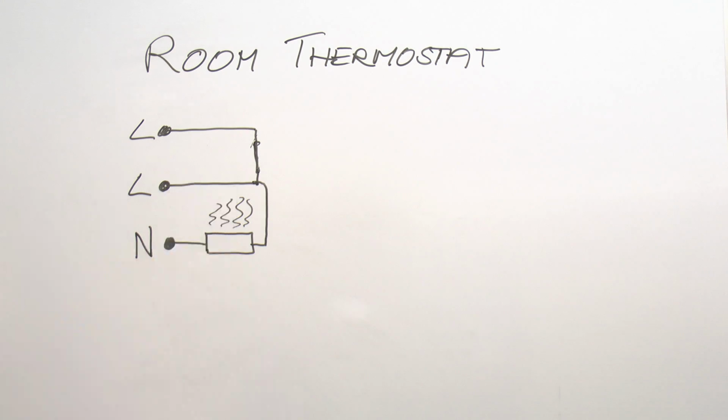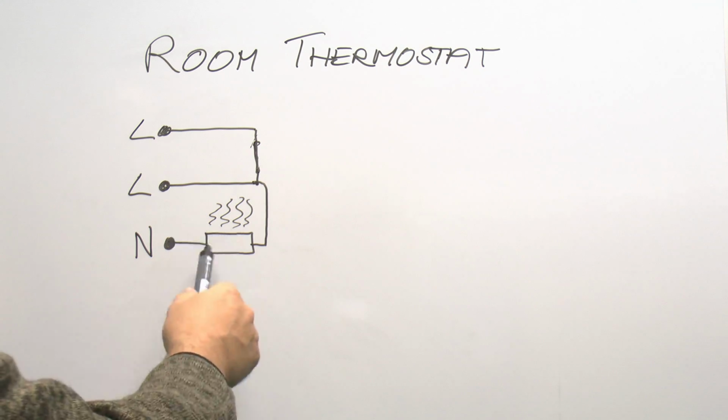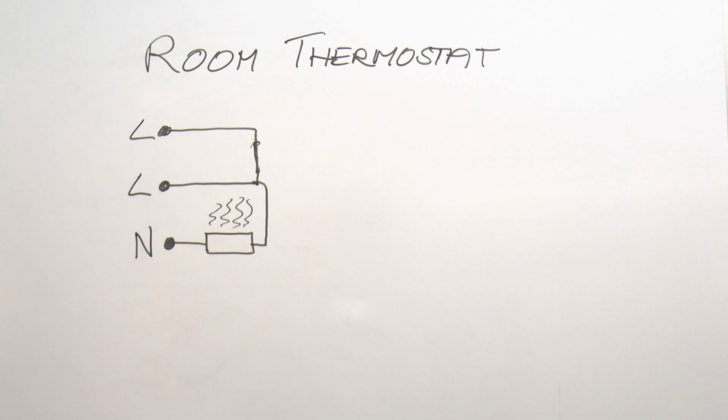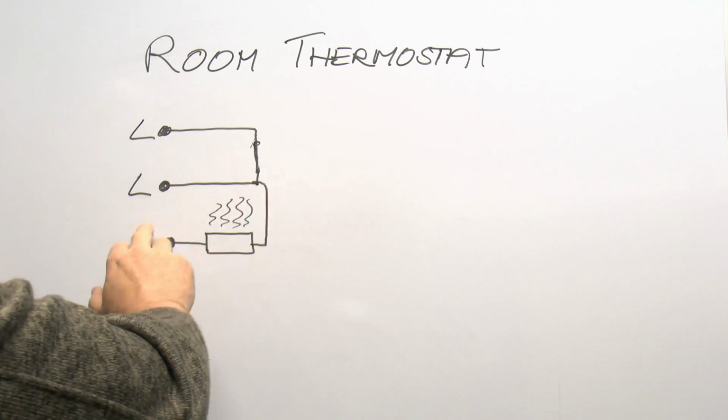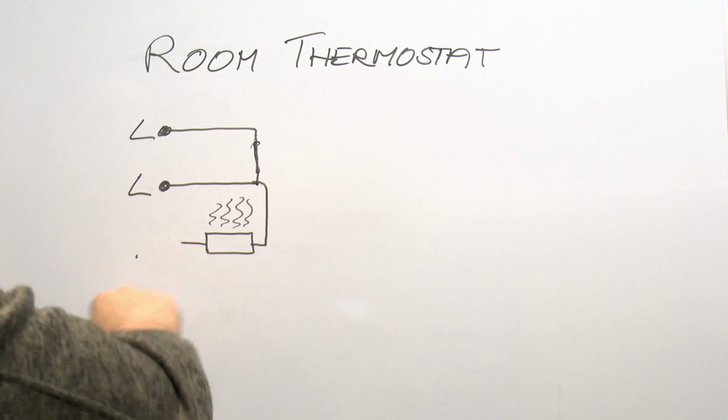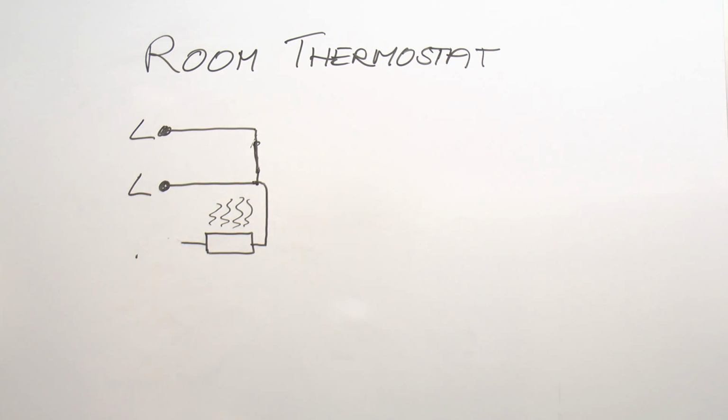It would result in fairly large temperature swings within the room. So it's purely there as basically sort of a booster heater to ensure that the contacts actually open and close rather more responsively. If this isn't connected, it will still work. So if there was no connection there, but you'll find that the temperature in the room tends to vary considerably as the metallic strip is fairly slow to actually respond.